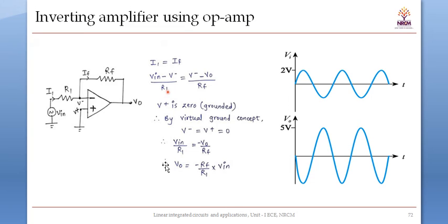So here in the inverting amplifier, the input voltage is applied to the inverting input terminal, and the non-inverting input terminal is grounded, and the supply voltages are given to pin number 7 and pin number 4. To pin number 7 plus VCC is applied, to pin number 4 minus VEE is applied. I have not shown it here in the op-amp, you have to show it. For pin number 7 VCC and pin number 4 minus VEE, from 12 volt to 15 volt you can apply.